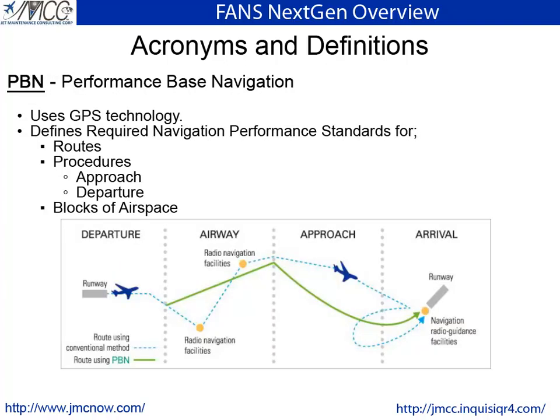Performance-Based Navigation, or PBN. Performance-based navigation utilizes the accuracy of GPS technology. It is a framework for defining a navigation performance specification along a route, during a procedure such as an approach or a departure, or in a block of airspace. In order to use these routes, procedures, and airspace blocks, an aircraft must comply with the specified operational performance requirements.